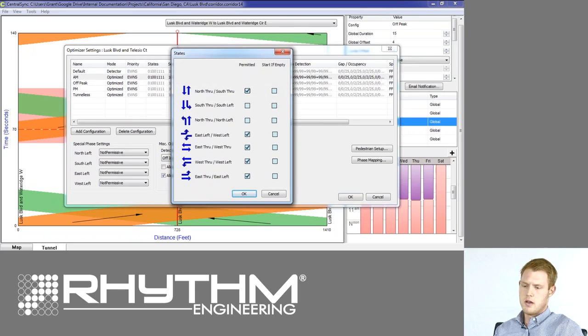In this case, this is what InSync considers its allowable states menu, or what phase pairs are allowed to run at each intersection. So in this case, certain phase pairs are allowed to run together and certain phase pairs aren't. So the ones that are allowable are selected and the ones that aren't are unselected.